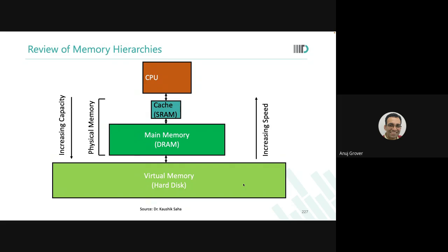Forget about what the DRAM intrinsic performance is. The fact that you have to go out of the chip onto the PCB, then to the memory chip, collect data from there and come back. Even if you scale DRAM performance, the majority of the delay is the bridge between the PCB and your processor. So it simply will not scale.